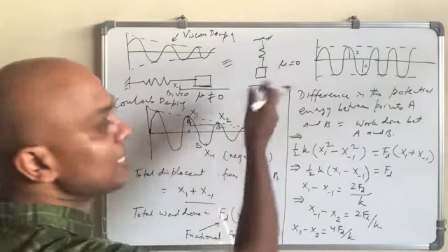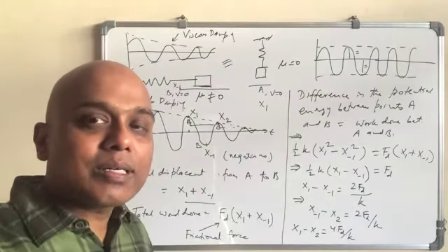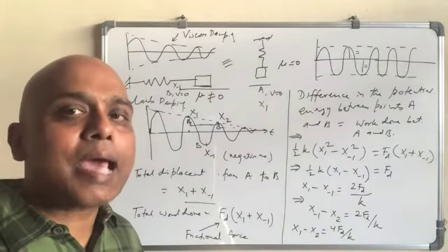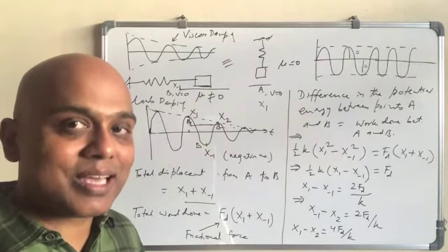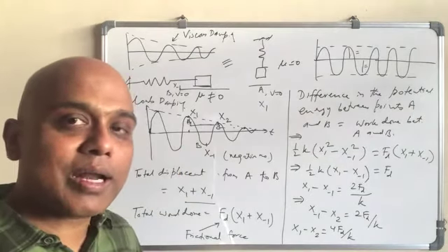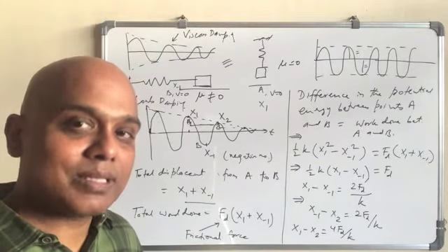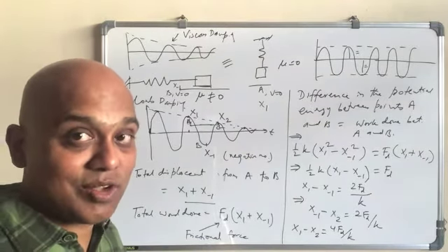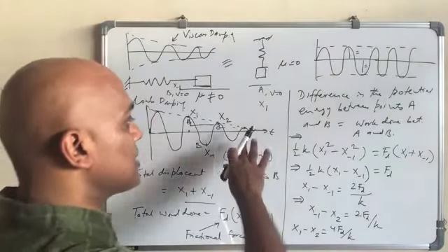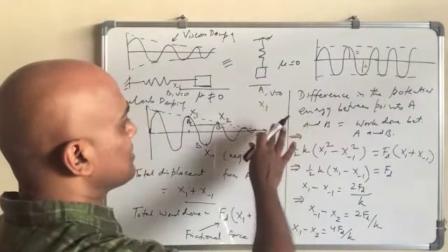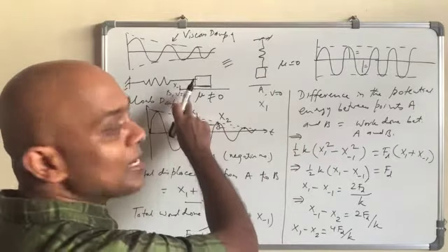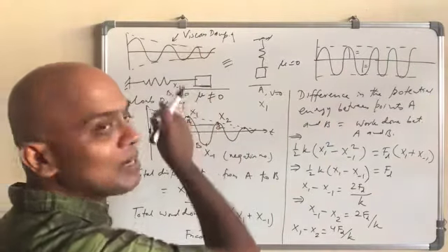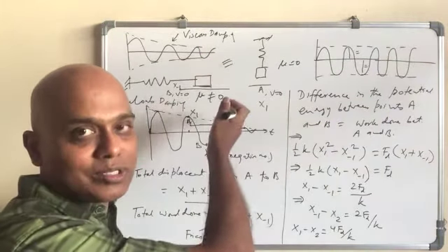Omega d comes from zeta, right? So omega n times root under 1 minus zeta square. But that is for velocity dependent damping. Here, it does not depend on velocity. Fd is constant. So in this case, zeta is actually 0, because this is not viscous damping. This is a different damping. The only thing is that there is energy loss.